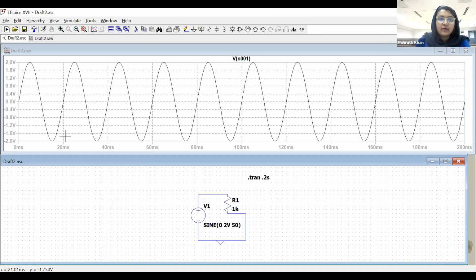So if we use our formula with peak voltage, we are also good, because it's 2 volts divided by square root of 2, which is 2 volts multiplied by 0.707. But as they are using peak to peak voltage, which is the double voltage, they are doing peak to peak divided by 2 into 0.707. Gotcha. So that's what we are saying here.